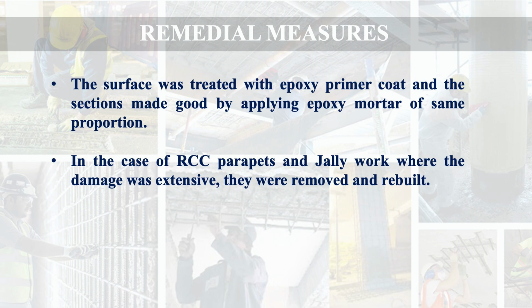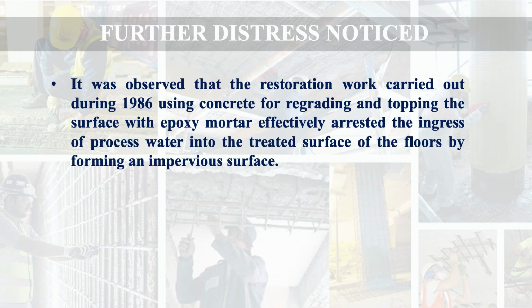Then what distress was noticed further? It was observed that the restoration work carried out during 1986 using concrete for regrading and topping the surface with epoxy mortar effectively arrested the ingress of processed water into the treated surface of the floors by forming an impervious surface.